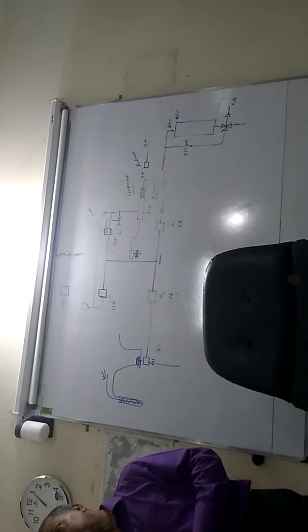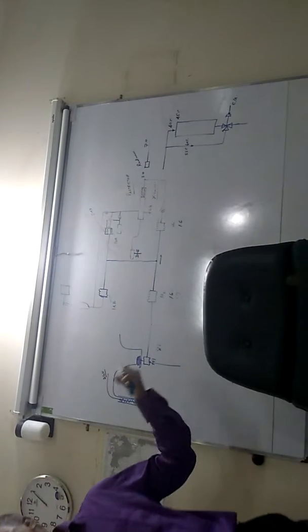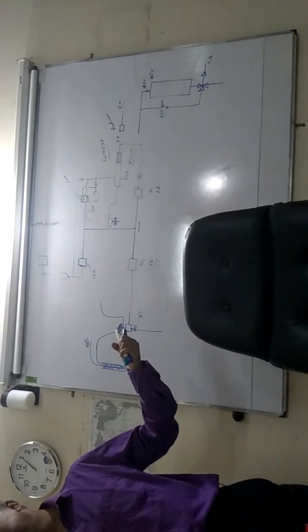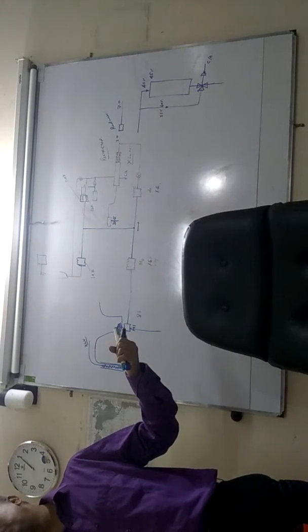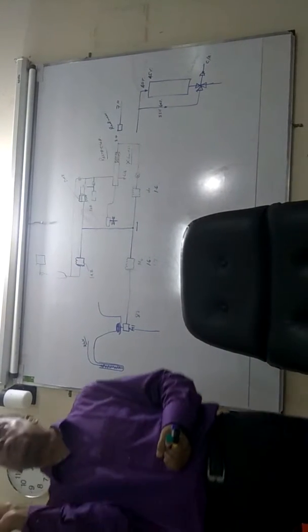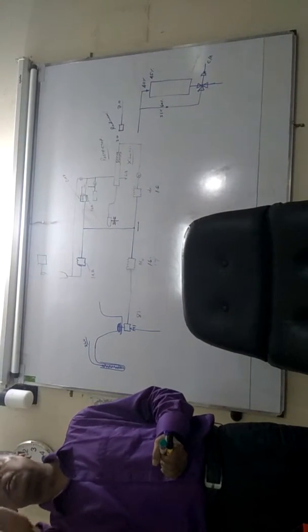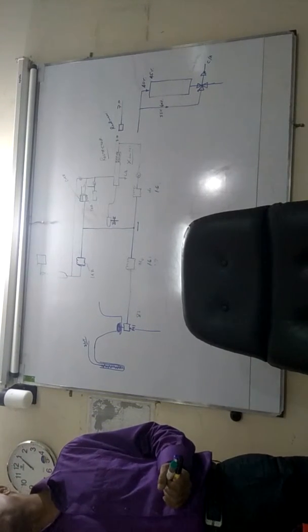D by 4, that is the maximum lift required. So if it is 0.7 millimeter, the valve dia, that is the nozzle dia, divided by 4, only 0.2, even less than 0.2 millimeter. Flapper is moving only maximum to minimum is 0.2 of a millimeter.